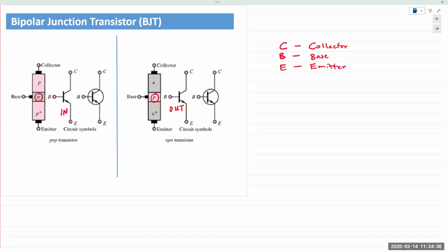Similar to the MOSFET and JFET devices, you have three terminals. For a JFET and a MOSFET, straight lines; for a BJT, it's angled. The arrow notes the emitter terminal. The base is always in the middle, so if you know the emitter, you know the base. The third terminal is the collector.